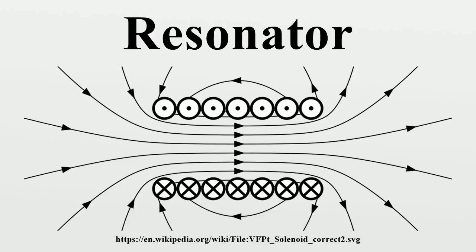The reflex klystron is a klystron utilizing only a single apertured cavity resonator through which the beam of charged particles passes first in one direction. A repeller electrode is provided to repel the beam after passage through the resonator back through the resonator in the other direction and in proper phase to reinforce the oscillations set up in the resonator.